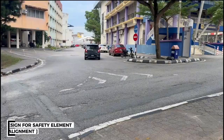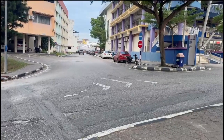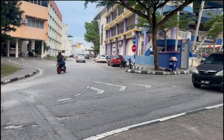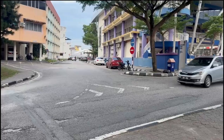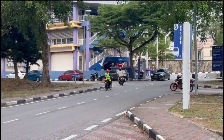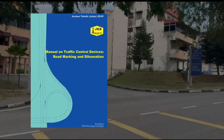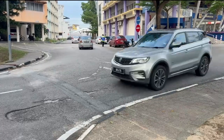The second issue involved poor vehicle alignment at the junction, where vehicles cross into opposing lanes due to unclear road layout and marking. To address this, clear lane marking, aid lines and directional markings should be installed to guide vehicle movement, especially at intersections. This improvement helps drivers maintain proper lane discipline and reduce conflict during turning movements. This mitigation is based on ATJ2/85 road marking by JKR, which outlines standard road marking requirements for safe junction operation.